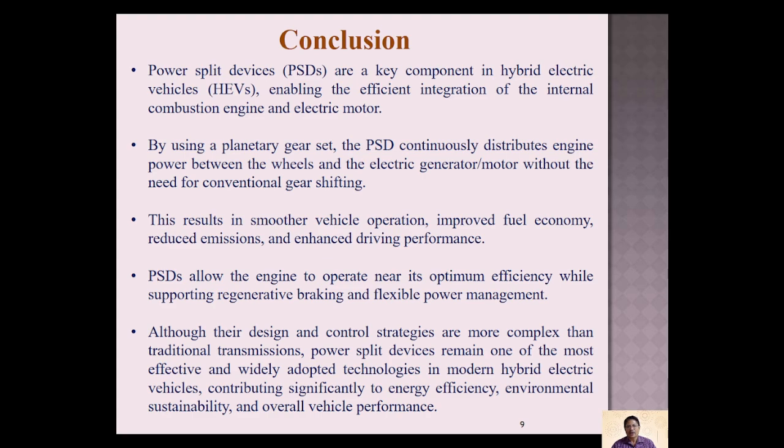In order to conclude this chapter, power split devices, PSDs, are a key component to the effective implementation of combined operation of the IC engine as well as the electric motor to maximize the efficiency of the vehicle. Using a planetary gear set, the PSD continuously distributes engine power to the wheels, whenever the electric generator or IC engine gives power. So it has smooth operation without conventional gear shifting.